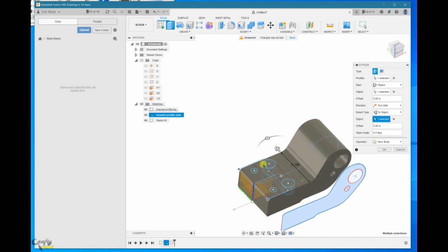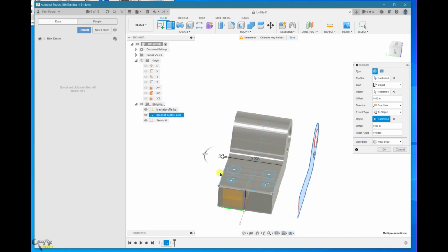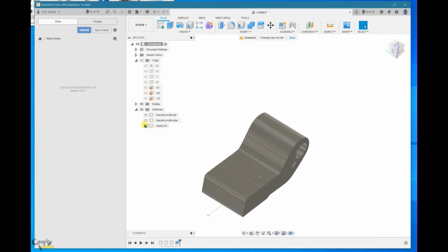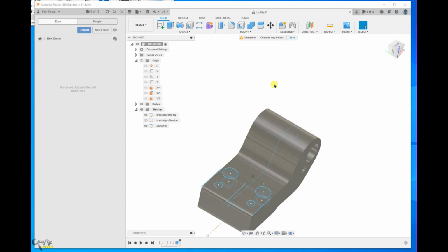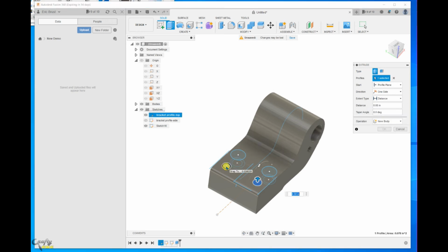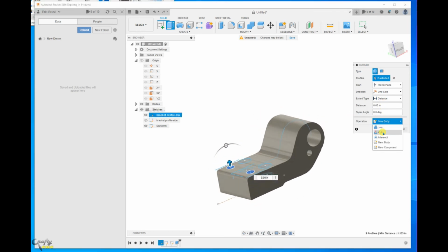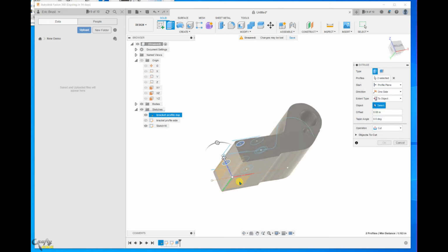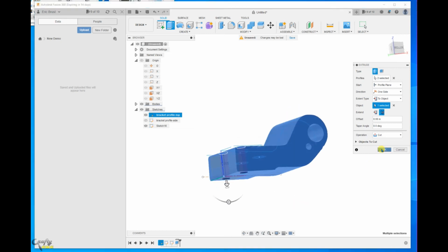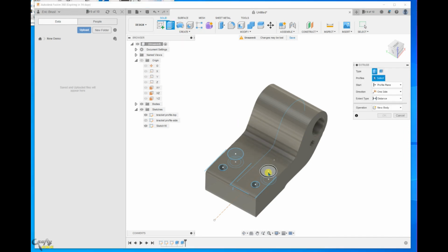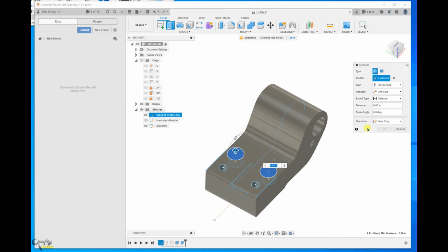Let's project that onto the set sides that we had recorded. We'll turn back on our top, and we'll extrude our bores in. Going to do a cut. Go down to the bottom surface. Grab the two counterbores.